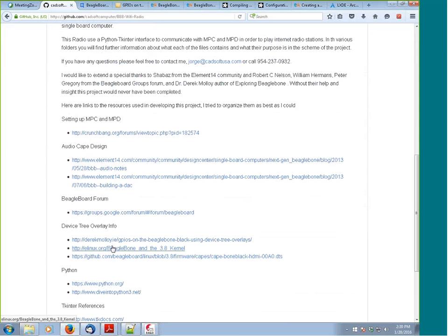Now, because it's transparent, you can lay several of them on top of each other, and when you lay one transparency over another, you can reveal new information, or you can block old information. Device tree overlays basically work the same way. By default, the Beaglebone Black has its built-in device tree, a few overlays that are set up at startup, and then any item that's connected that requires certain peripherals or anything can request to have another overlay thrown on top.